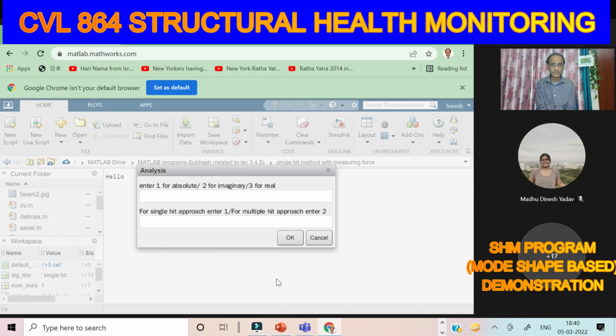With the absolute data, it's easy to identify the peaks. Okay, so I am here giving the input as 3. Then it asks whether it's the single hit approach or the multiple hit approach. Single hit, multiple hit, you can very easily relate. Single hit means we are applying force at one point, and in a single go we are acquiring all the data from all sensors. So I'm entering here 1.